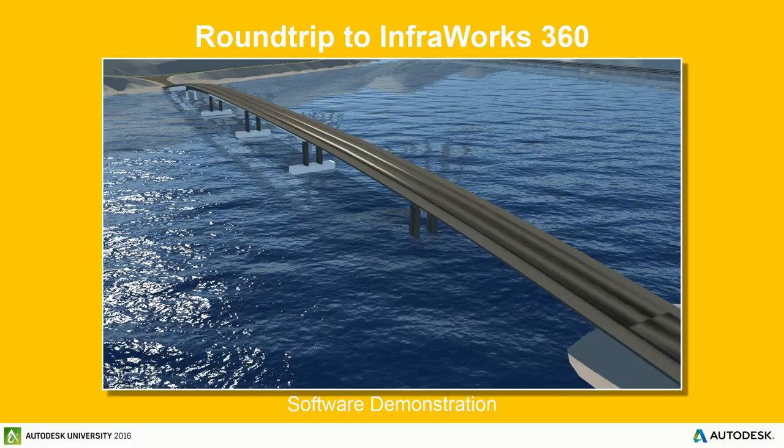I understand that, of course, within InfraWorks, it will create the bridge for you, and taking it into Revit, you can add the reinforcing, do those additional type of engineering and analysis. What's the true purpose on bringing it back in? Just for contextual purposes, because when we work with InfraWorks, it's a very easy tool to very quickly design the bridge in its context according to the site. If you didn't have that and you just had Revit, you would have to build the Revit bridge from the Revit perspective and not have the site conditions, which means you have to bring in the site conditions, build the bridge, and then take a look at it from that context.